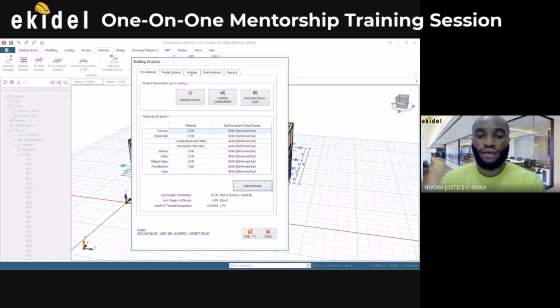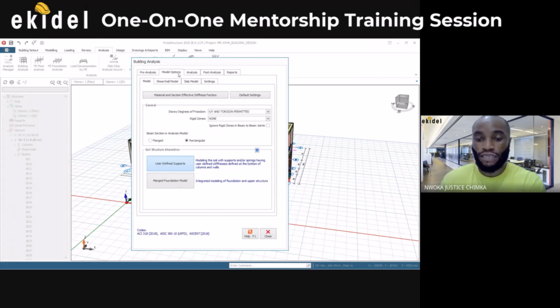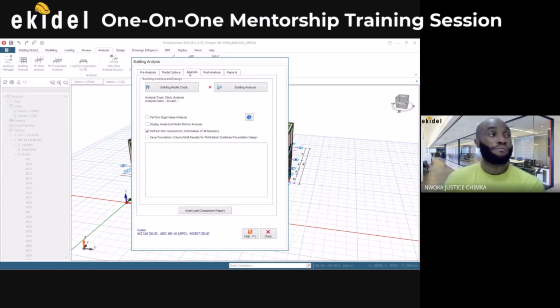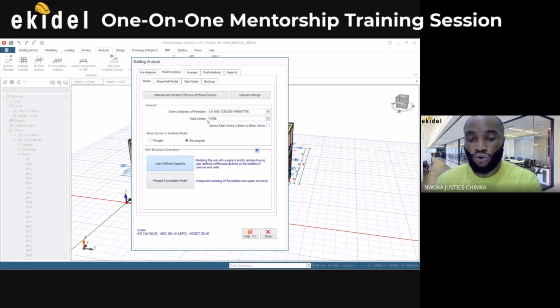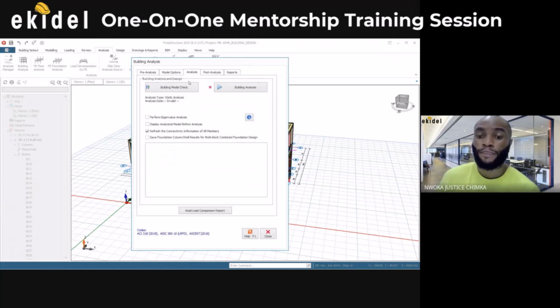Now move to this analysis tab here. Leave everything here as default for now. Although most times you can see it says rigid zone. Most times people choose 25% as the rigid zone, and most times they still pick none. So move to the analysis tab. Then once you come here, you can click on Building Analysis here, and hold on for a while for it to display.